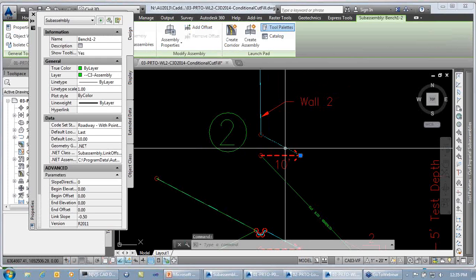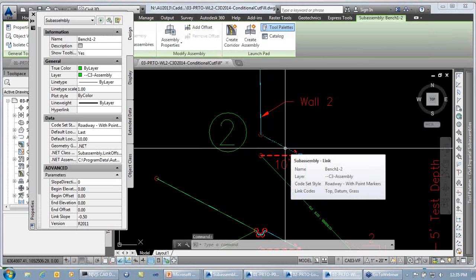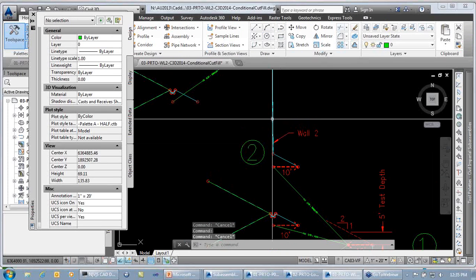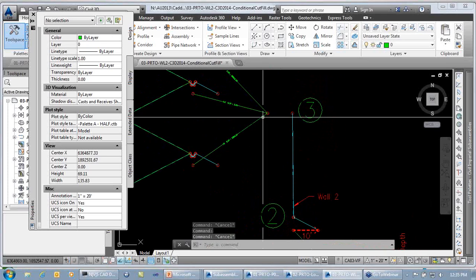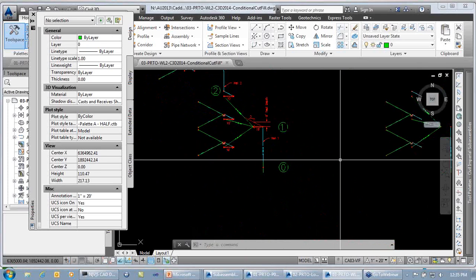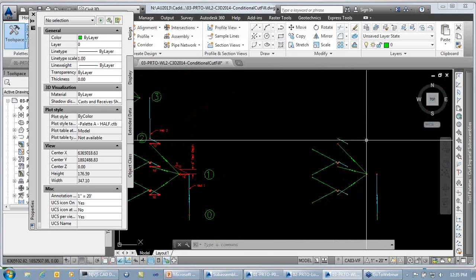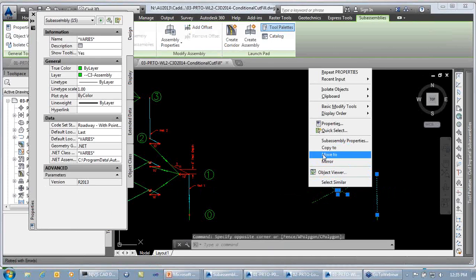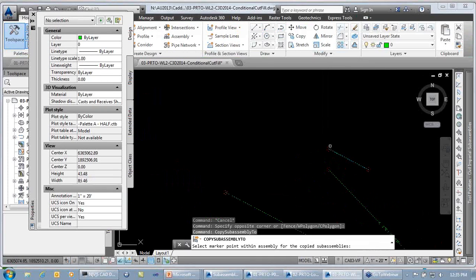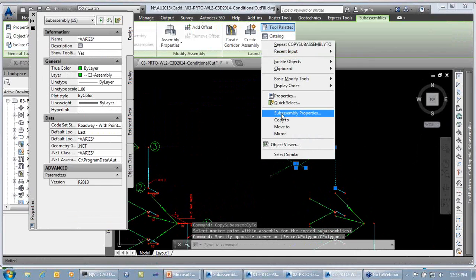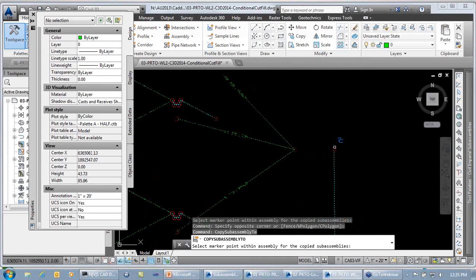And then on this one, we have a 10-foot bench with our 2-to-1 slope. And then we're putting in the second level of wall, and then just the pattern repeats from there. Okay. To do that, I've got this example. I've built it out to this location, and it's just as real simple as once you get the first piece done, it's a right-click copy to place it on the end of there, and then I can just keep repeating this, right-click, copy to on however many